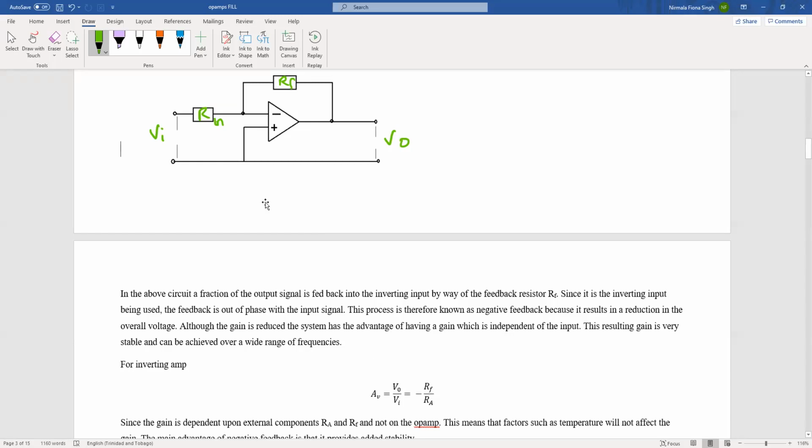In an amplifier, we have 2 inputs that go into your circuitry. We have a positive input and we have a negative input. And what this negative input does is flip your signal. So if you had a nice positive signal here and you feed it through your negative input, you are going to get a flipped signal as we just saw.